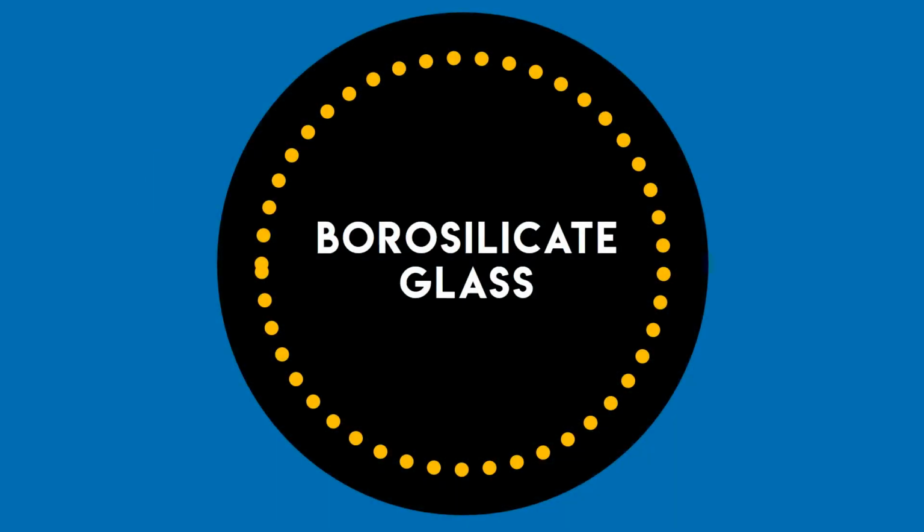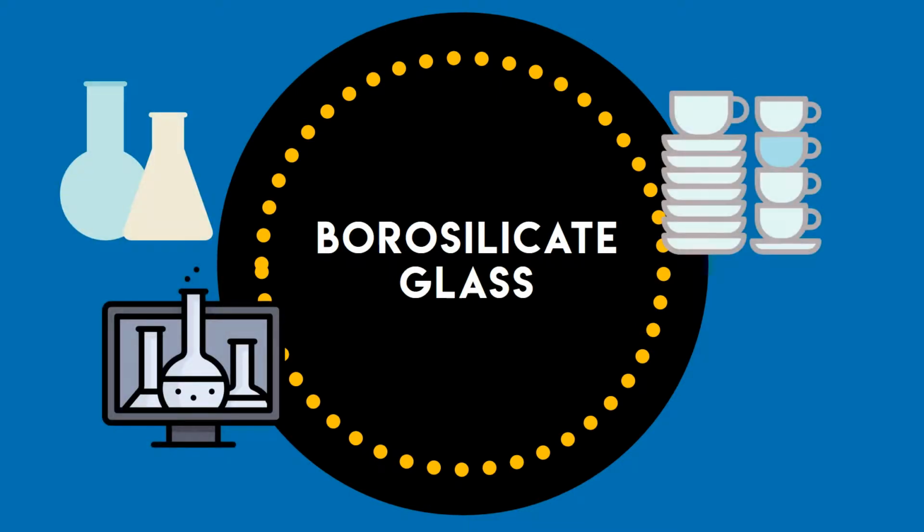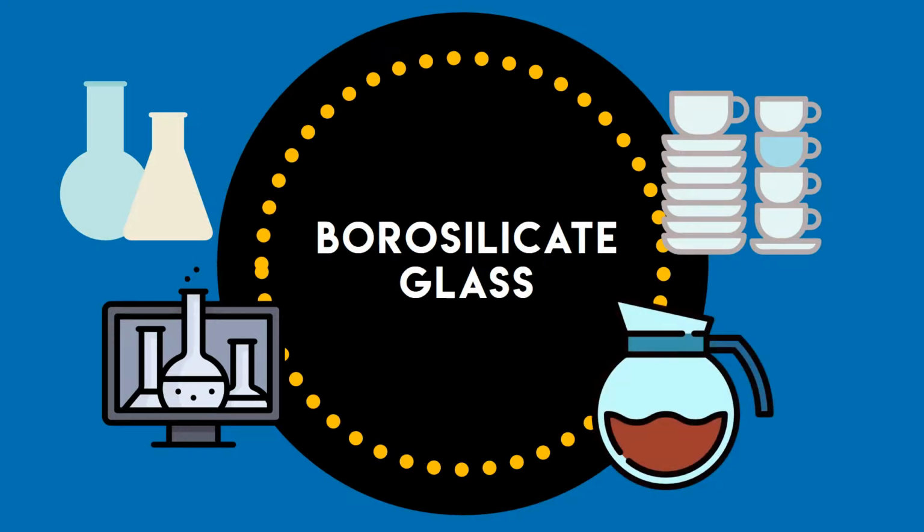Borosilicate glass, commonly known by its trade name Pyrex, is a type of glass with silica and boron trioxide as the main glass-forming constituents. Borosilicate glasses are known for having very low coefficients of thermal expansion, making them resistant to thermal shock, more so than any other common glass.